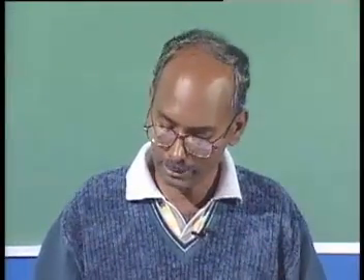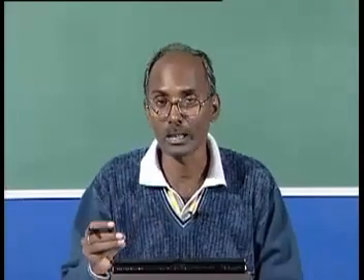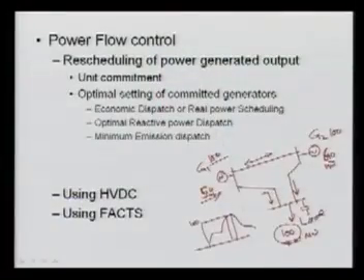Why? Because this megawatt is not fixed. This megawatt keeps on changing. As I said, here the load profile, maybe you are going for this one, and let's suppose this is your 100 megawatt. So you can say only for 1 or 2 hours it is 100 megawatt, for the remaining portion it is less. So there may be a possibility when one unit is sufficient, so why should we run the second unit? So we can decide which unit should be on and which should be off. That problem is basically known as the unit commitment problem.